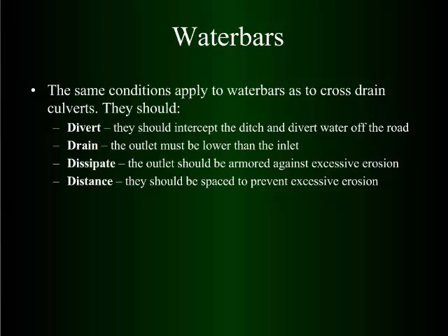If you haven't put water bars in your road before, you've got erosion problems, you want to correct it. How many do you put in? There is no particular formula that you use. What I would suggest is you put some in. If you still get erosion between them, you need more. It's not very scientific, but if you don't mind having them in, more is better. You probably can't have too many from a drainage standpoint.